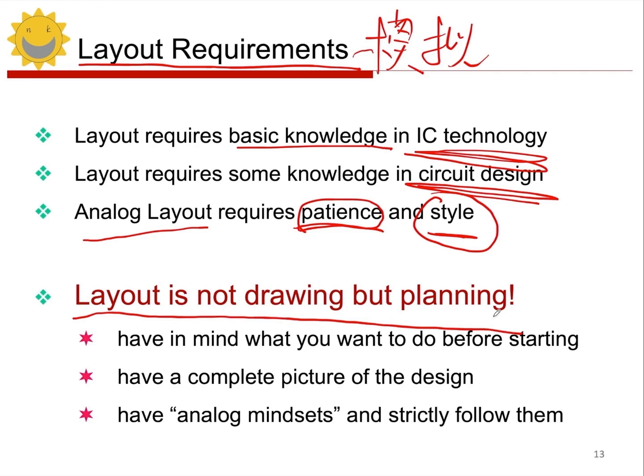Before drawing, have a complete concept of the layout. Consider which components need to be matched and which need to be isolated. This requires a plan. You can't just draw as you go. Otherwise, creating a good layout is difficult. Plan ahead how to draw it. At the start, sketch rough drafts before the actual layout.